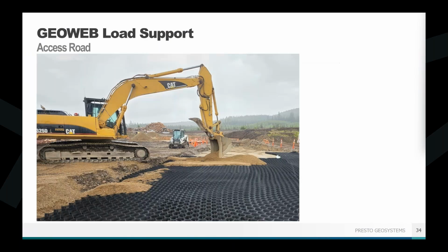So as I mentioned, the infill material had to use limited fines to help promote that stormwater flow and the infiltration capacity. And that was another reason to use the woven geotextile, an enhanced woven geotextile, because it does allow for water to flow freely in both directions without clogging or binding. A non-woven geotextile would get clogged very easily, and a slit tape woven does not actually allow water movement in both directions. The water gets basically trapped by the geotextile, creates potential pore pressure buildup issues. So just something to keep in mind.